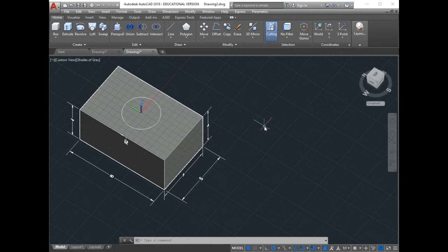So there are two ways to go with the user coordinate system. Either you define each point one by one, defining the origin first, then a point along the x-axis, and then a point on the xy plane, which takes a lot of time. You can make it very short by just clicking on a face and simply clicking on one of the points on that face. Be sure, guys, that when you pick up that point, your face becomes what? How do I know that I'm picking up a point on a face? The color will change from gray to blue, and then simply click accept. Clear, guys?